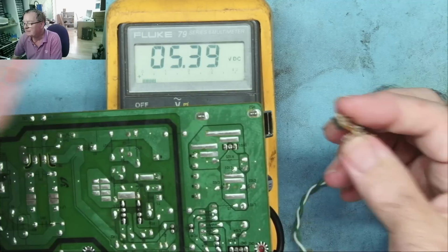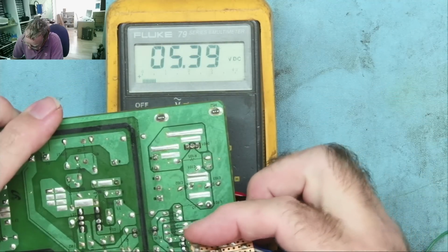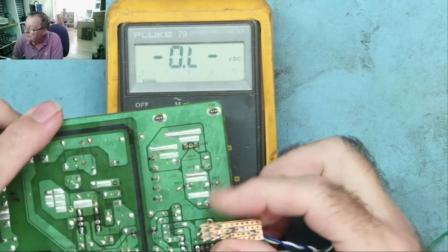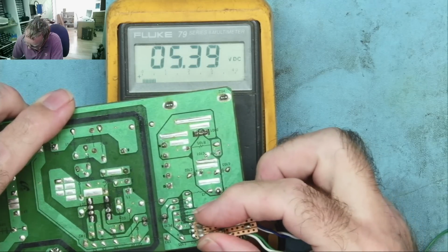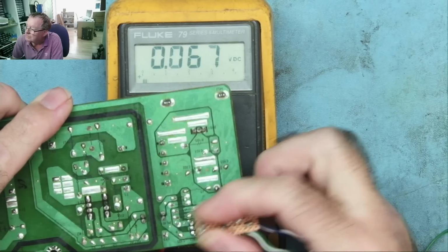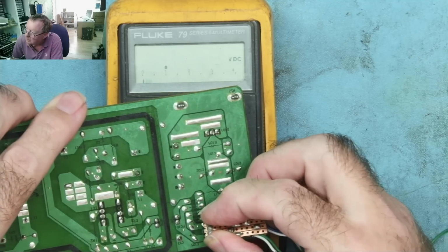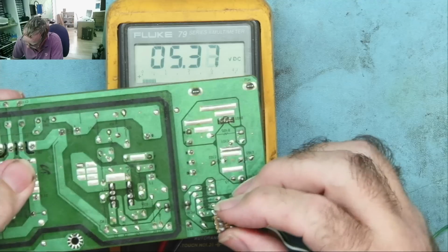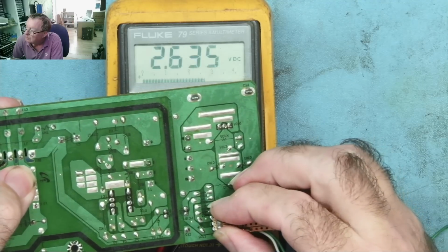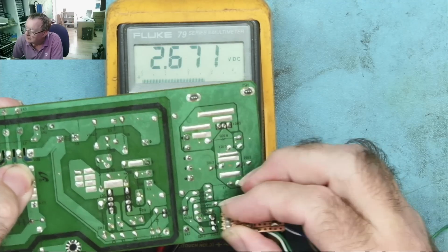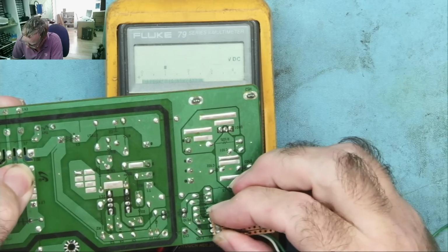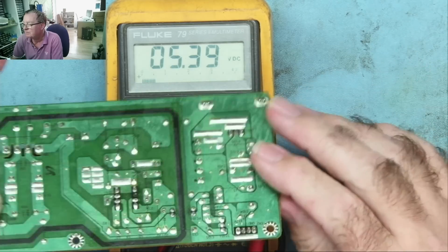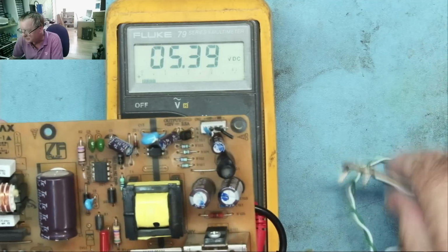If it still says 5 volts or something, the chances are it is faulty, but just take it out and just be sure. There may be something to do with components around it, like if it reads short again, take that and test it. Okay, that was just reading short because I had effectively shorted the thing with the pins. So you can connect a little tester like that and test them in circuit.